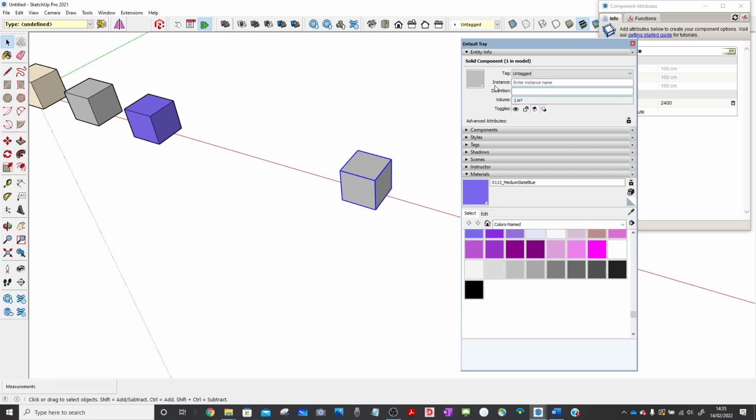I'm sure you can. The first part of my six-part code will be the project number, 1301, underscore. That's my project number, let's just say. The next part of my code is: is it superstructure, substructure, what level is it? So it's 1. So that's superstructure in my code.